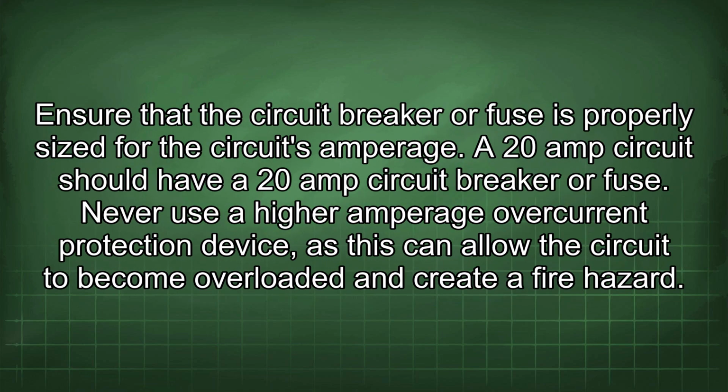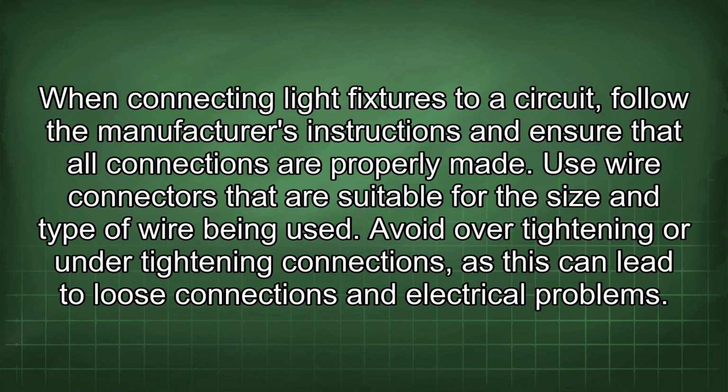Ensure that the circuit breaker or fuse is properly sized for the circuit's amperage. A 20 amp circuit should have a 20 amp circuit breaker or fuse. Never use a higher amperage overcurrent protection device, as this can allow the circuit to become overloaded and create a fire hazard.